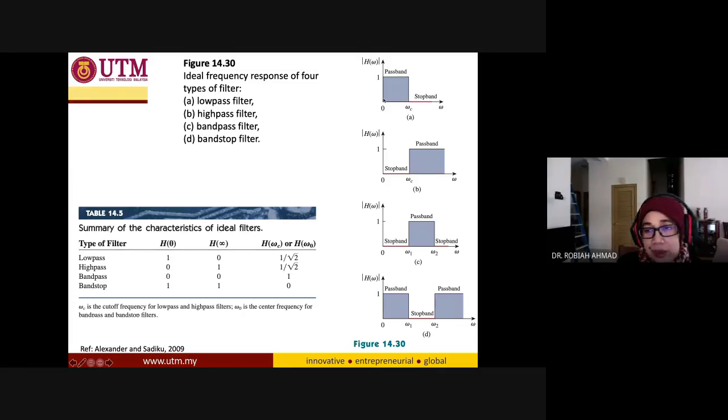And then if you look at from 0 to infinity of the omega, the frequency, so from 0 to omega c, a certain frequency that is cut off, right? So that is why we call omega c the cutoff frequency. Okay, so the signal gain will be 1 here, meaning that whatever you send into your filter, you will get exactly the same, 1 to 1.